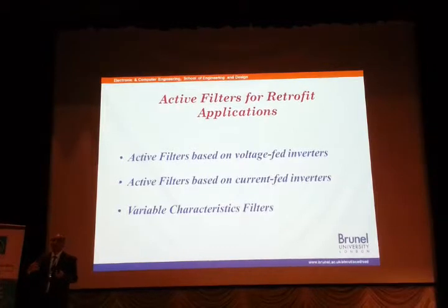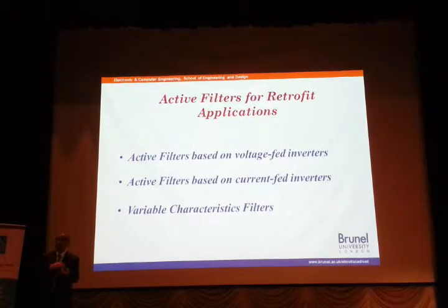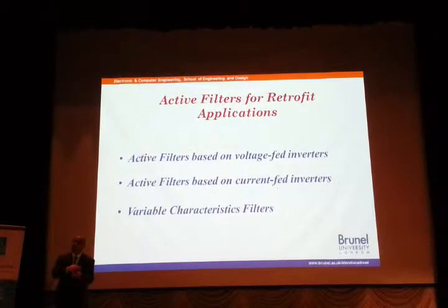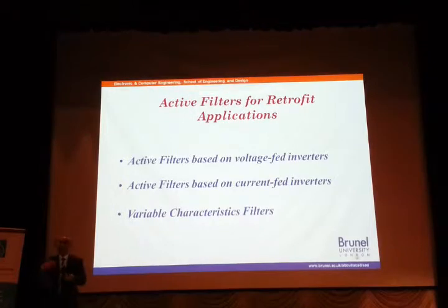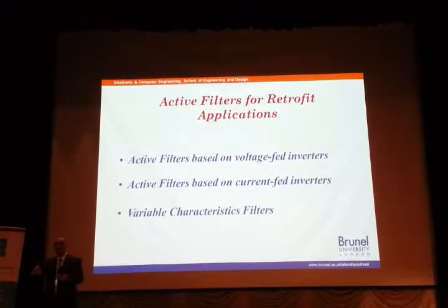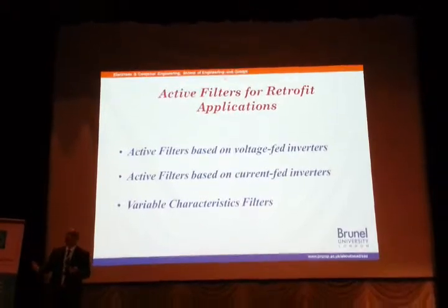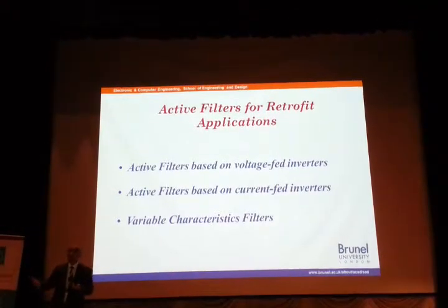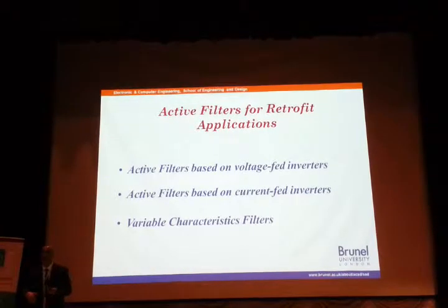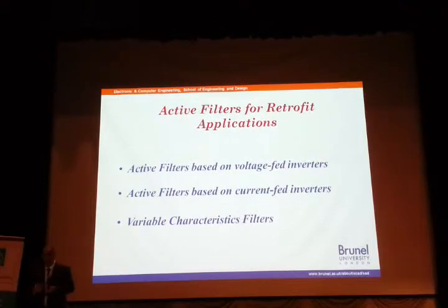Now what I'm doing, I'm using another inverter, but the other inverter I'm using as an active filter, in order to compensate or correct the distortion created by the first inverter. So in another way, we try to solve the problems caused by power electronics by also using power electronics, okay? So we try to clear our own mess, if you might call it that way.